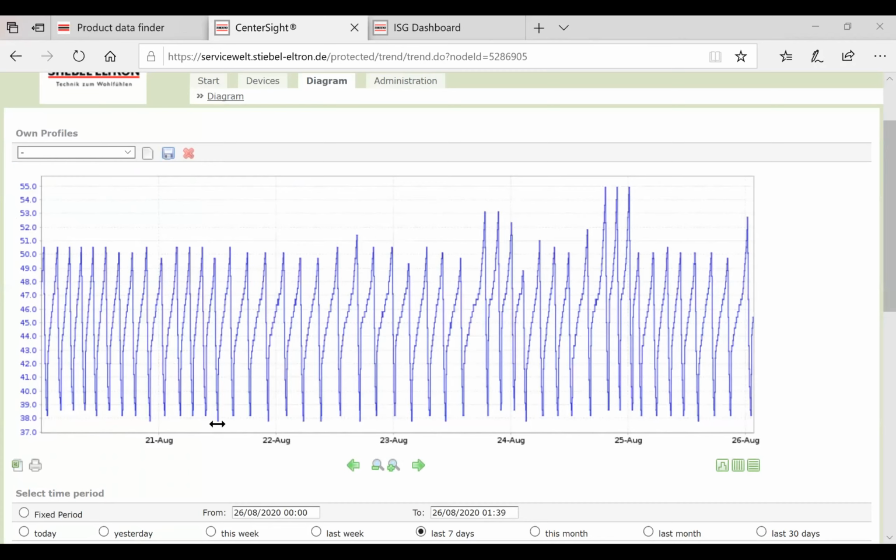Now, normally, if a buffer temp is heading up at such an angle like that, it's because the heat pump is making more energy than the heating system is distributing. So sometimes what we do is we make the heat pump less aggressive. We turn the heating curve down. So we'd like to flatten that curve out, so the heat pump's just running, just trickling in what temperature is actually being lost by the distribution system. So things like buffer temperature.